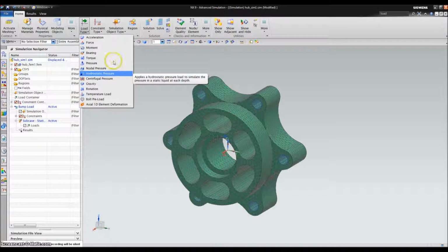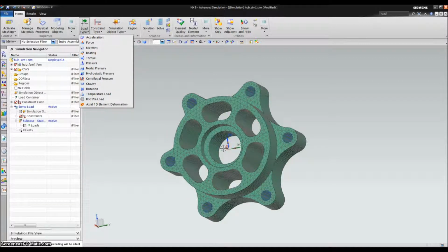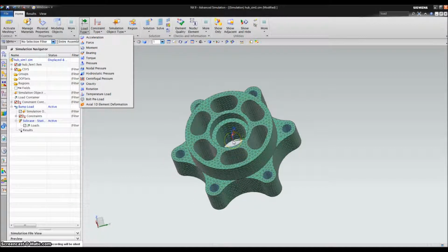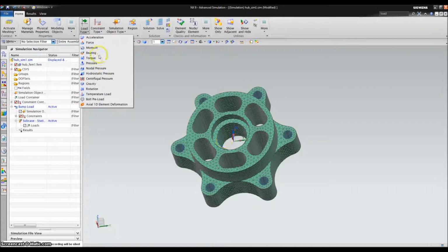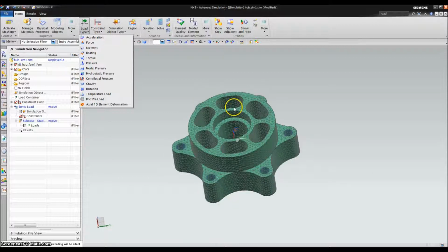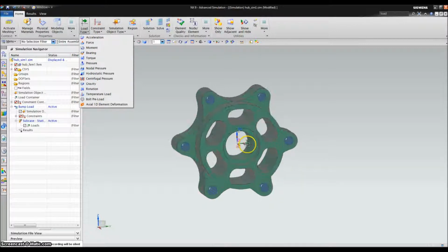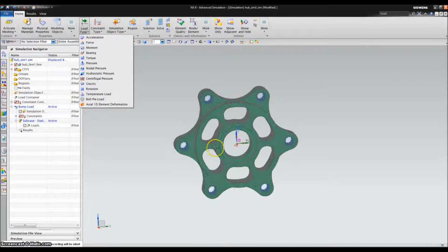But anyhow, the load we're going to be using is the load of the wheel onto the middle of the hub. So if I bump the wheel upward very hard, it's going to be applying a large force right into there. And that force is going to be a bearing force, such that the force straight up is going to be of much greater magnitude than the forces off to the sides. And in fact, that force is going to decay sinusoidally until it reaches 0 and 180 degrees.